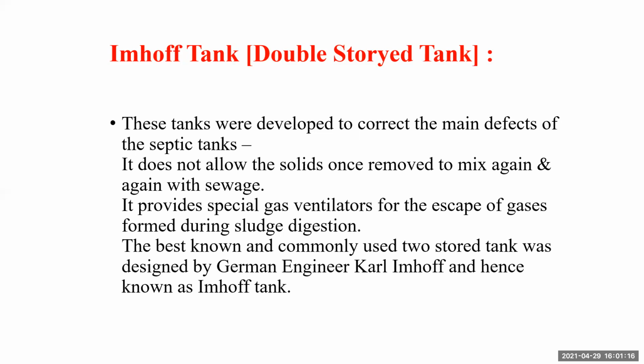It provides special gas ventilators for the escape of gases released during sludge digestion. And number two, it does not allow the solids settled at the bottom to mix with the sewage.